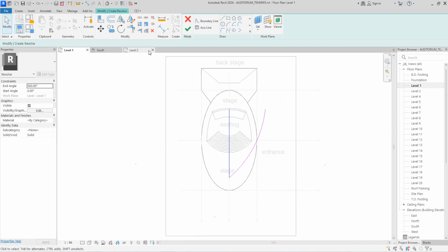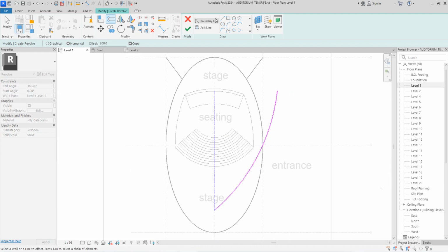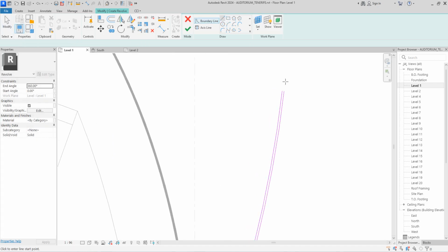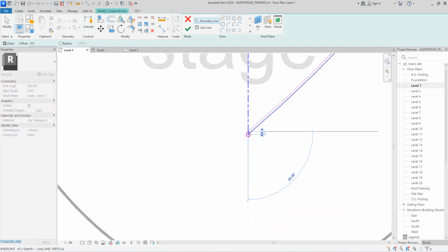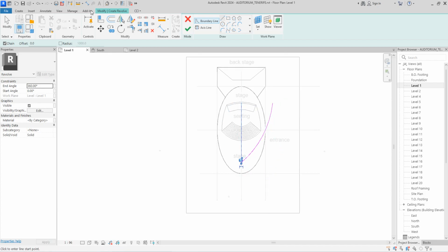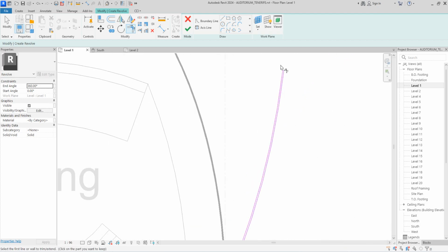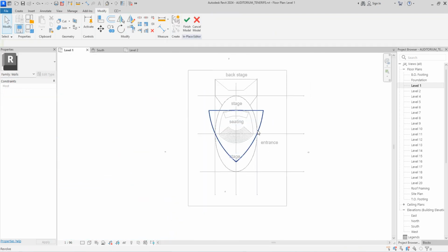Now what I do next is create the offset, which is 200. Good. That is the thickness of the wall. Then I draw this, pick this one, draw, and get this one, right? You do this by clicking and say finish, then finish. So you can click finish and see what you form. This is what you have drawn on this one.